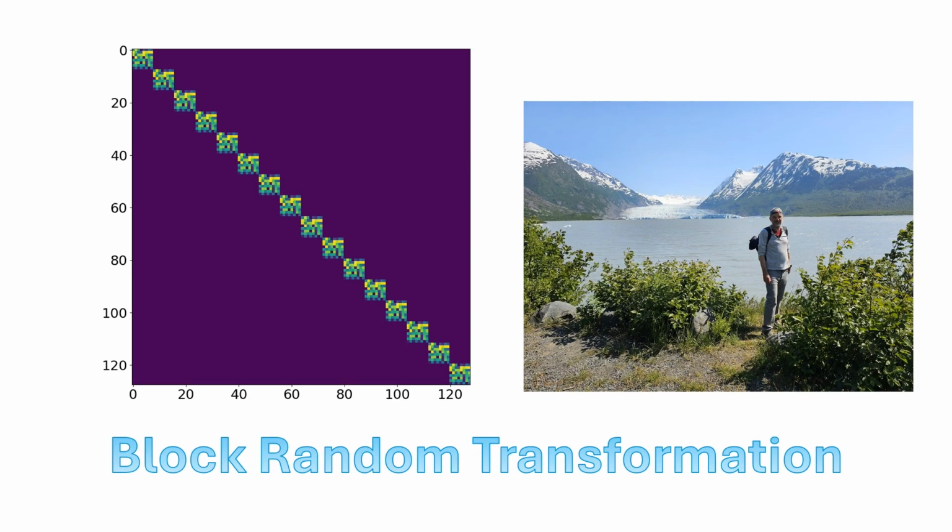structure. So here's an example of where we're going to break the image into 8 by 8 blocks, and in this case we'd have a random transformation of each block in the image. So we take the image, and this is a common strategy in compression, measure each little block in the image, do projections on those separately, and then in this case, an 8 by 8 block, we'd have 64 pixels. We might keep, let's say, 8 or 12 of those projections, and so we've got automatic compression by a factor of 8 or so in the image that will allow us to be more efficient in our measurement system. And we'll use this in Chapter 8 to think about feature-specific measurement strategies.